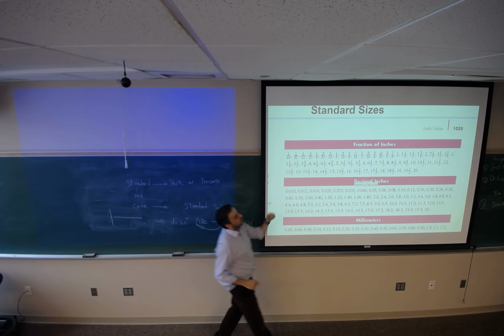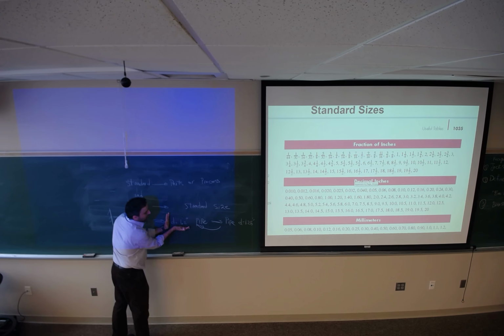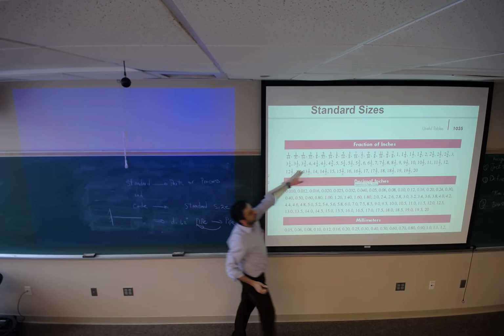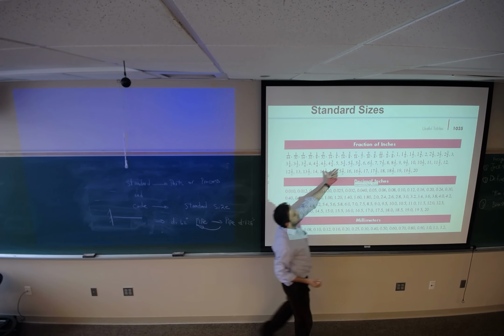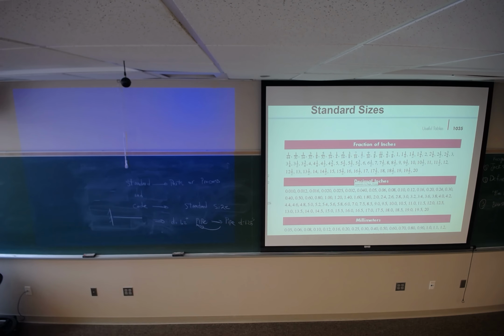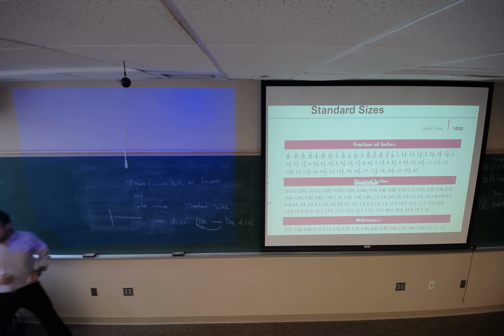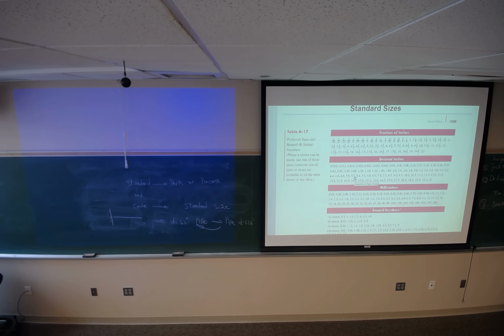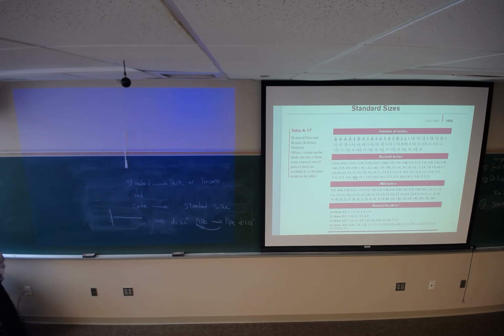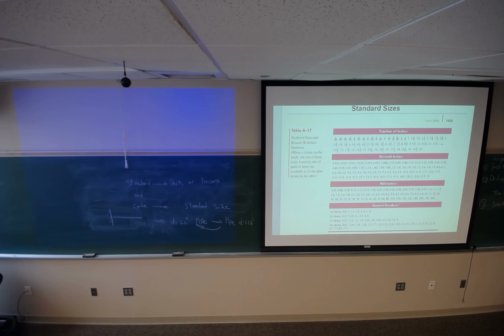So in your design, if you come out with a dimension or size that you couldn't find as an exact number in the table, you round it to the closest standard size. So 1.2 inch, I round it to 1.25, which is one of the values that I can find in the table. So why do we do that? Because we want to reduce the cost in our design.